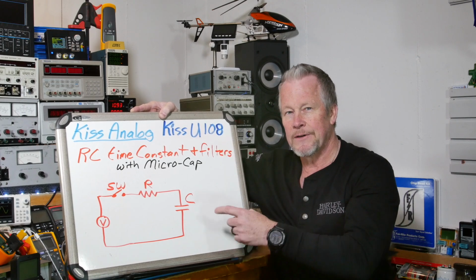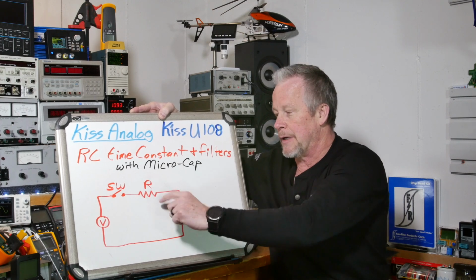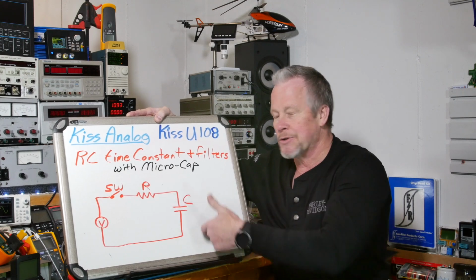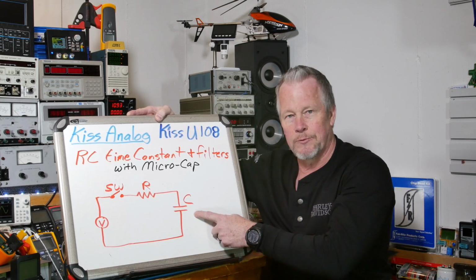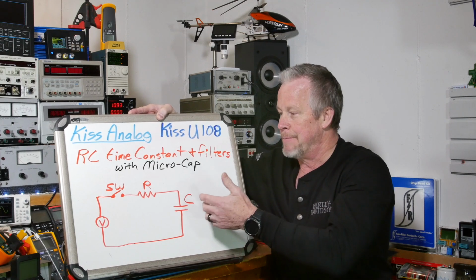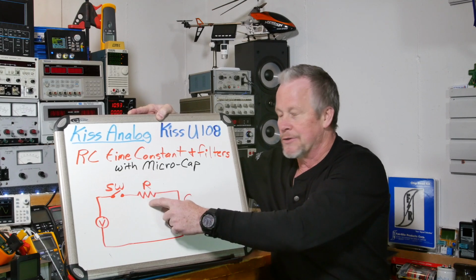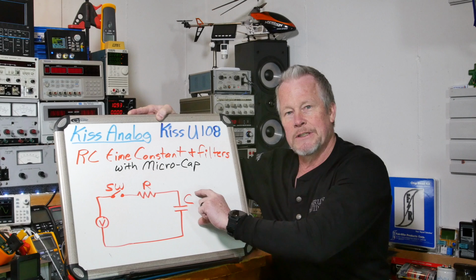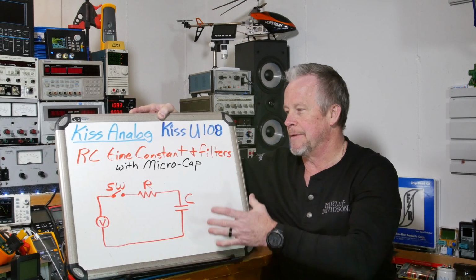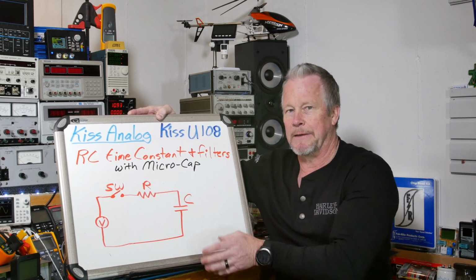During the transient analysis portion, there is current flowing, so you get a voltage drop, voltage drop. When you get to the DC analysis, current's no longer flowing, unless this is a real leaky capacitor. Then you might have microamps, that kind of thing. But practically there's no current flowing, so there's no voltage drop here. So all the voltage is here. That's the basic analysis between the transient and the DC, what's happening in the circuit.